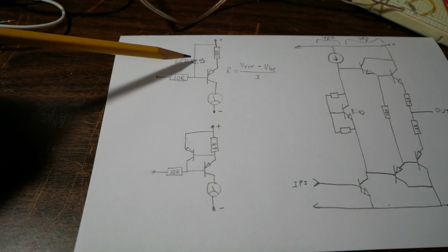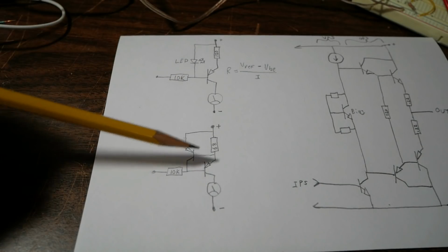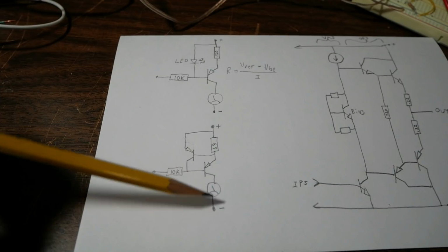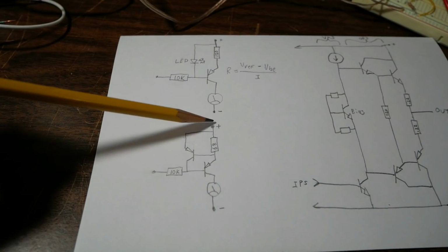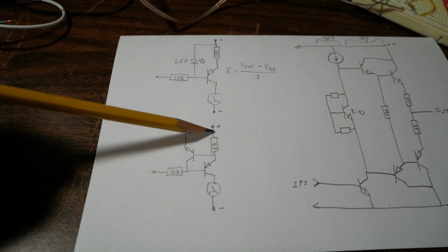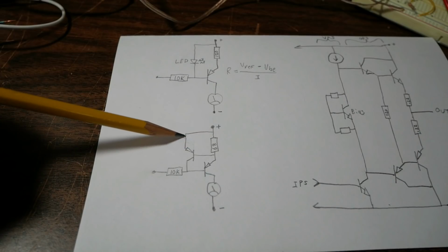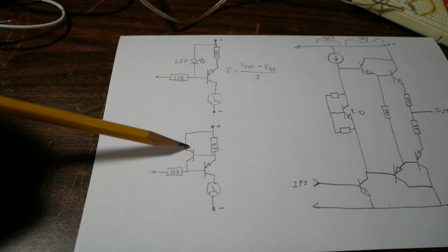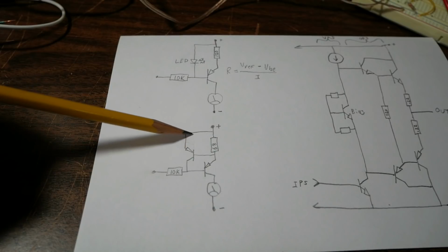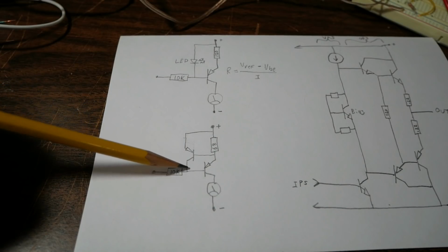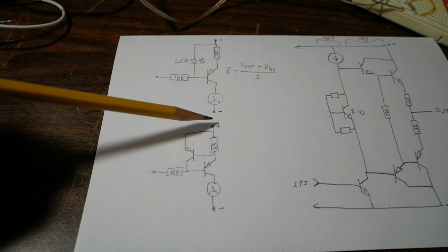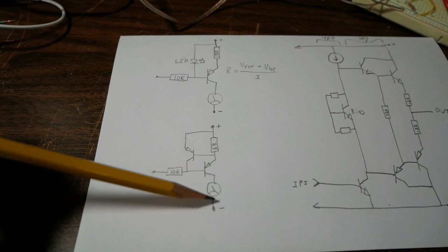In this circuit, we replaced our voltage reference with a transistor, but the function is pretty much the same, really. So what happens is, if this is carrying the designed current and you increase the voltage across the device, heavier current's going to want to flow, increasing the voltage drop across this resistor. So more current is going to want to shunt around that resistor through the base emitter junction of this transistor. When that happens, you turn this transistor on more, and it's going to shunt current away through its emitter collector junction around the base emitter junction of this transistor, thus reducing the current, and it brings it back into check.